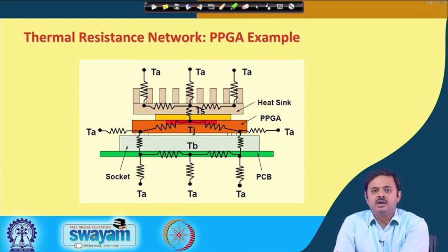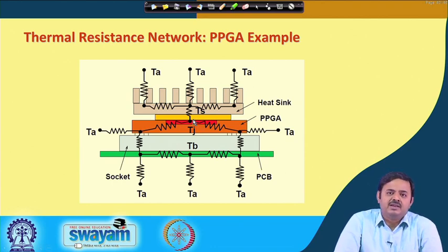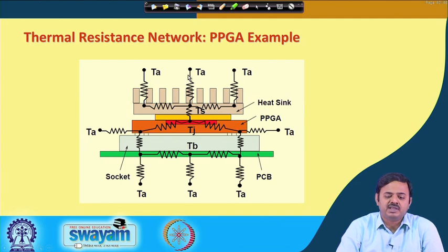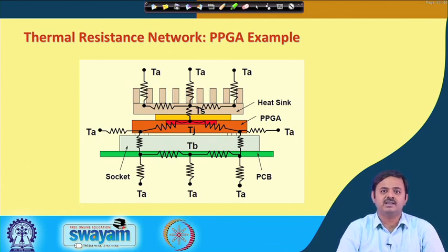It is very likely that if you do this whole analysis, you will see that the thermal resistance in this downward direction is very, very large compared to the upward direction into the heat sink, and that is the whole idea. So, as a result, most of the heat, maybe 90 to 95%, goes in the top direction as shown in this picture, and a lot less comes down in the bottom. But that may not be the case if this heat sink was not there. Then we do not know what will be the split. It may be 60-40 instead of 90-10.